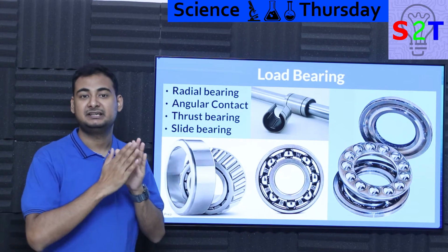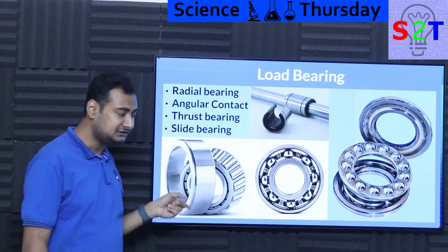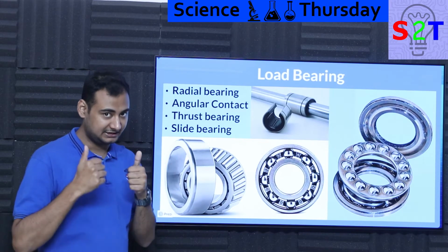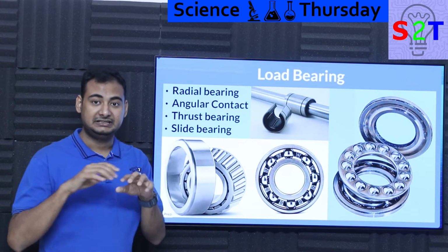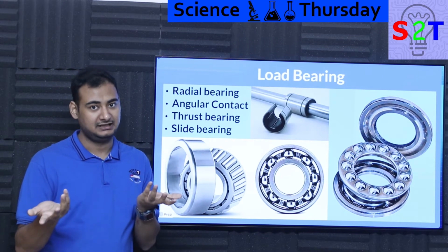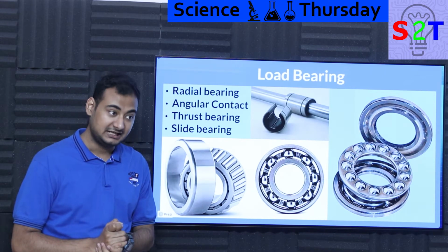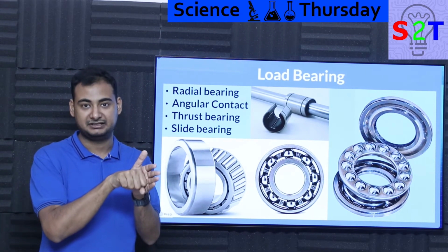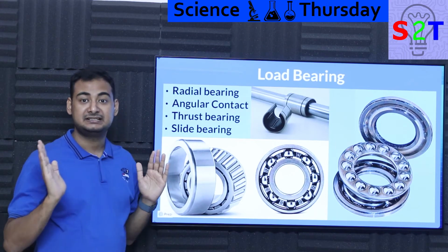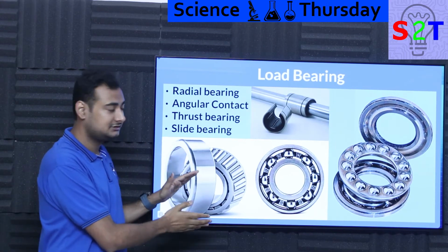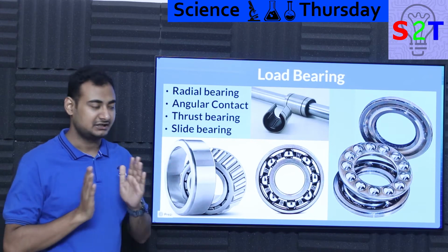Because of the roller elements, it can dump that load without damaging the inner race and outer race. So that's awesome. And because it's angular, even if you take a high speed turn, like a 20-30 km/h turn, it has a lot of tonnage load acting against it. In those situations, this bearing can still deposit that load from the axle to the chassis without any issue. It can still manage that.